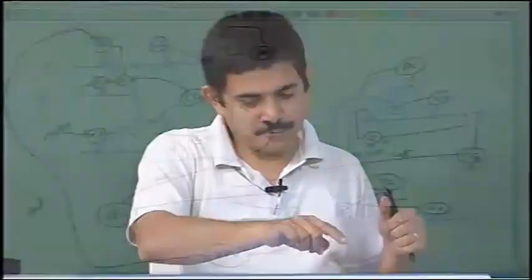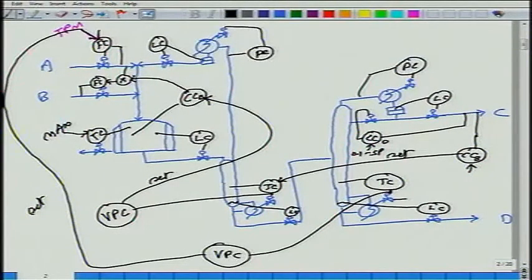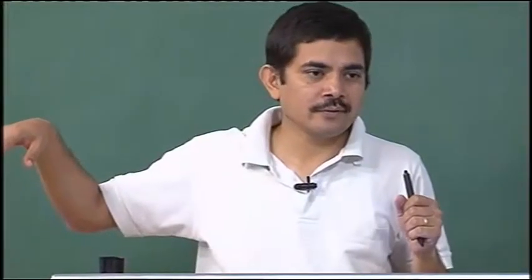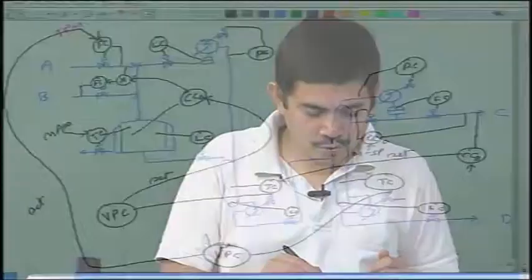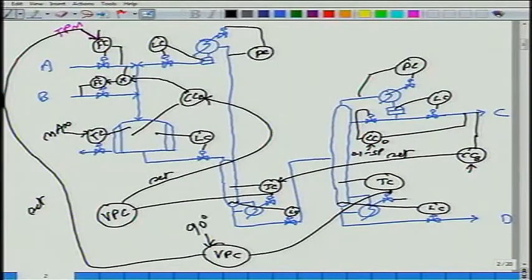The problem with this approach is, because you cannot have too much C leaking down the bottoms, it is important that the amount of C leaking down the bottoms is maintained, right? You want tight temperature control. Because you want tight temperature control, that means the boil up must be allowed to move. Therefore, for example, this VPC, you may only be able to go to 90% of maximum boil up. Similarly, this VPC, you may only be able to go to 90% of maximum allowed boil up.